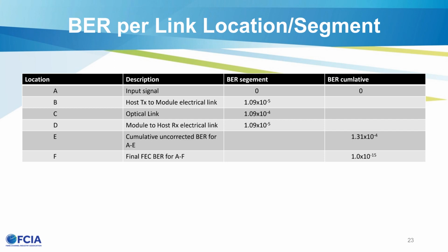And this has been a big change for everybody in mindset too. No matter what kind of standard they're working on that commonly uses FEC now, a common parameter people look at is the number of corrected FEC code words, and whether there are uncorrected FEC code words, which you don't want. For every Reed-Solomon code word for the 544, 514, you can correct 15 10-bit symbols.